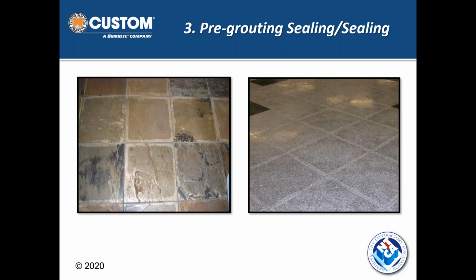And so the sealer is not going to discriminate between the edge and the body of the stone. People will say, well, the sealer is failing. Well, the sealer doesn't indiscriminately fail like that. It enhances what it can absorb into. And if it can't absorb into the edges of some of these pieces of stone, and again, notice it's not every piece of stone on the slate and not every edge, speaking to the variation and the potential for each material or color. But at that point, these are rip out and replace. That's a 3,000 square foot residential slate job, and that was about a 5,000 foot commercial granite job. You cannot fix those. Those are all rip out and replace.